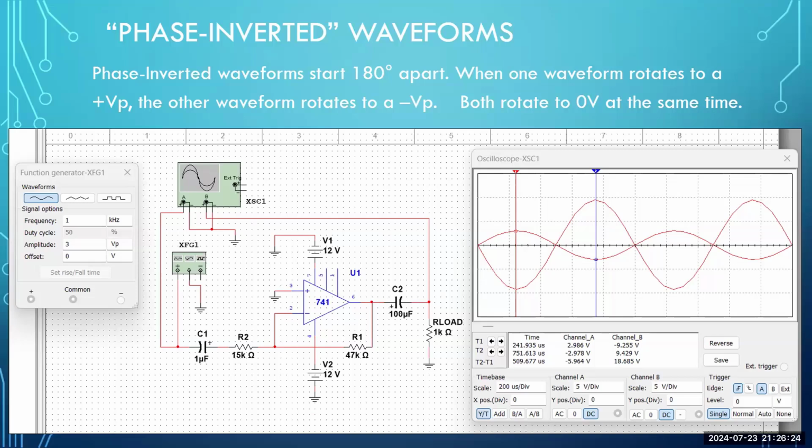Then, if you take a look at channel B of the oscope, channel B has a red wire that comes down and goes all the way to the right, and it goes to the top of the R load resistor, the 1K ohm resistor. So what we're measuring is a difference between the waveform going into the circuitry at C1 and the waveform coming out of all that circuitry at C2, going into the 1K ohm load. So input of the amplifier to the output of the amplifier. So this is a true amplifier circuit.